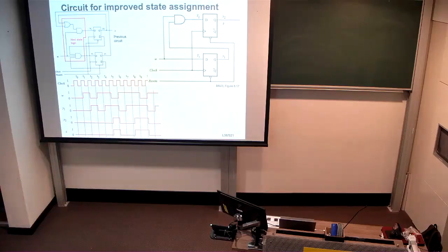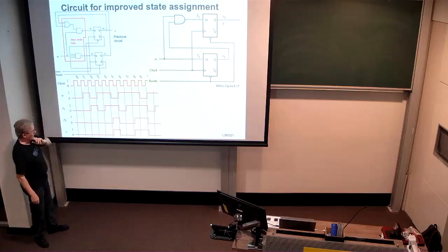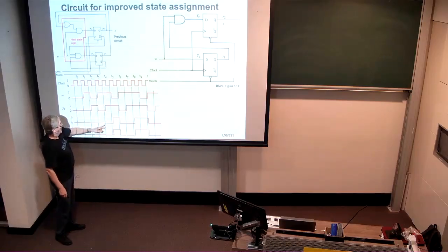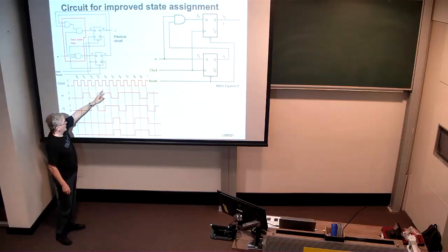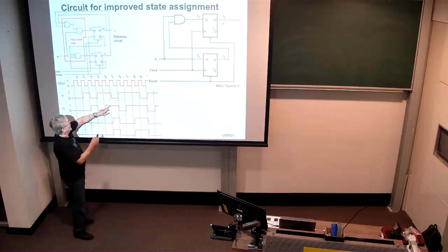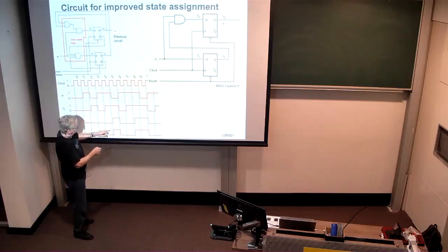Okay, so the same analysis can be applied to the timing diagram that we saw before. We see, for example, at the start of T4 on the rising clock edge, W is 1, therefore Y1 goes to 1. On the next rising clock edge, W is still high, and therefore we see Y2 going to 1 as well, and since Y2 is 1, Z is 1, right?